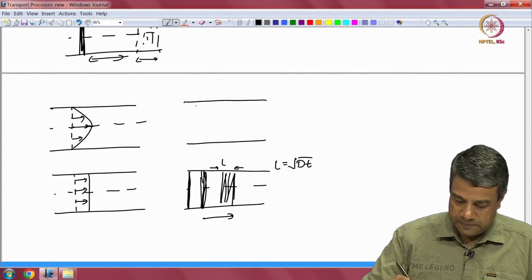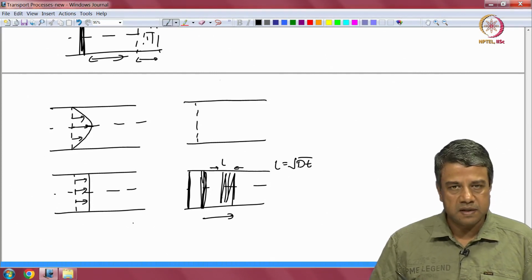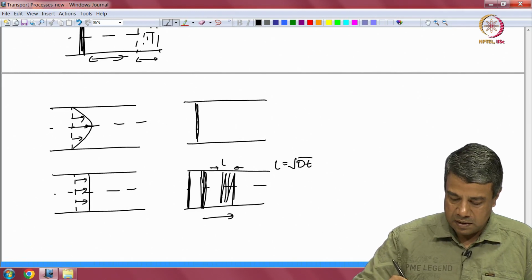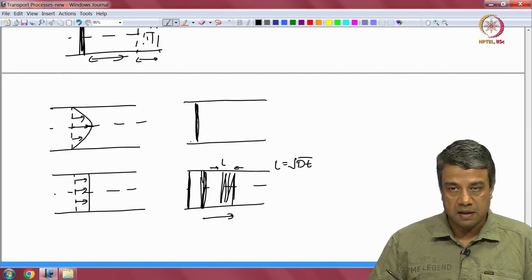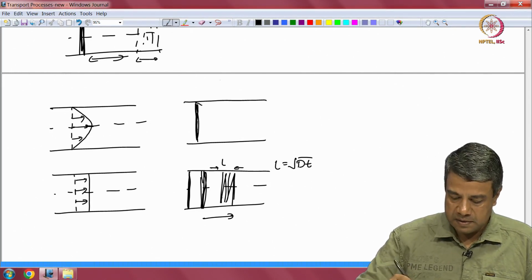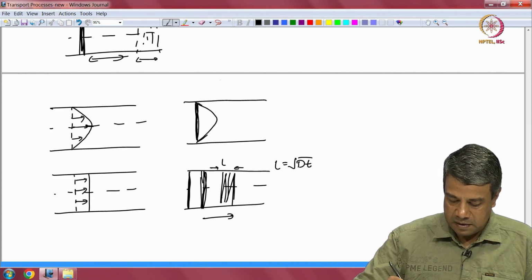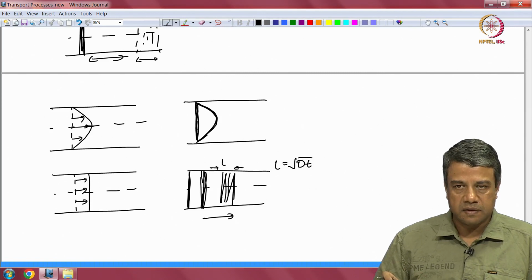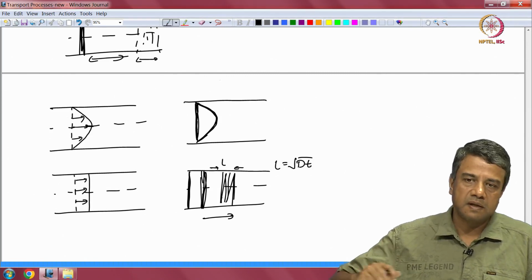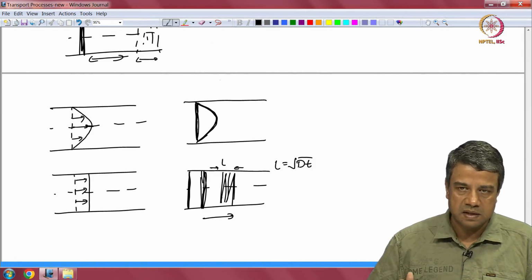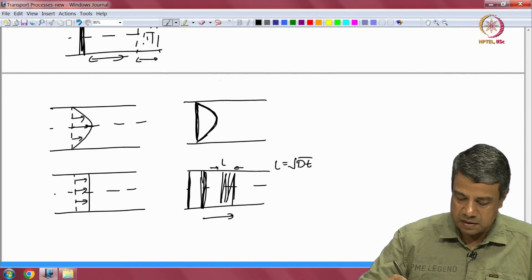This, on the other hand, in laminar flow, the velocity is 0 at the wall. It is large at the center. So, if you look at how this spreads, this will spread something like this. It will diffuse along the length, of course, but the center will be carried further downstream and the wall is stationary. So, it will spread a much larger distance.